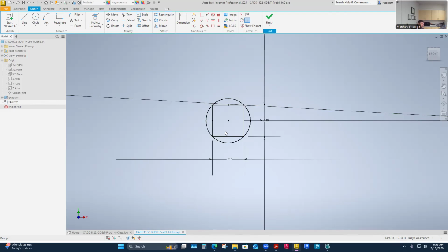Maybe, yeah, and it's 54% more tolerance zone if you added up all the square. I think in my little video that I posted in the resources for this week, he just shows the difference of the area of a length times width here versus the pi times r squared. Sorry, I should know this, I teach math. But yeah, this increases by 54%. It's in your book too on page 449.